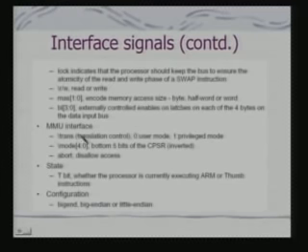And this MMU interface is the memory management unit. This memory management unit actually manages the memory, and it takes care of the fact that if you are in a user mode, you are not accessing a memory area which is allocated to software which is expected to be executed in a privileged mode.